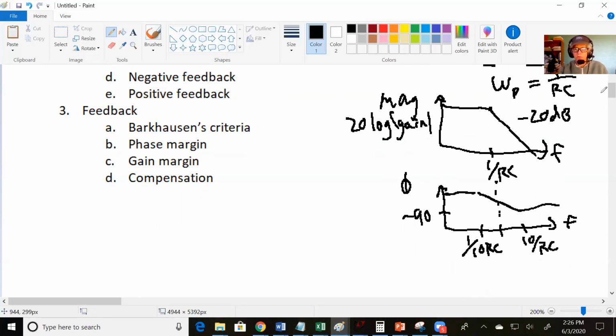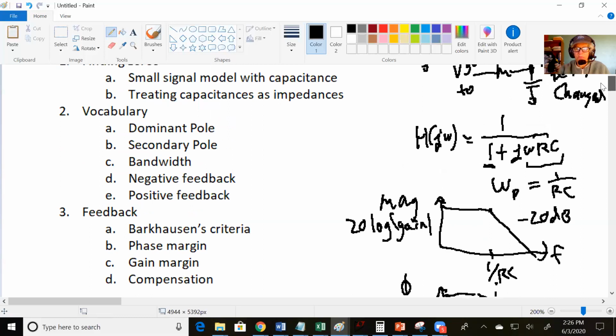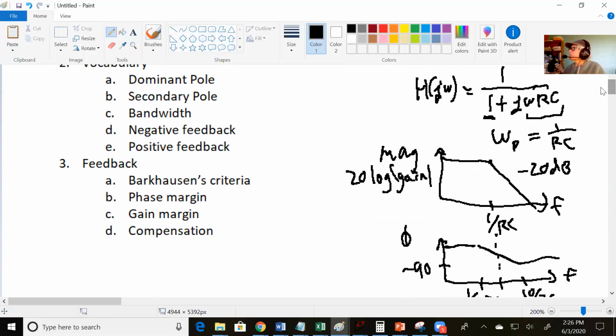But what was my point? Okay, so we've been able to find the pole basically using a quick method, just not having to do small signal analysis, just drawing in the capacitances on the transistor level circuit. But there's one value that you can't find without doing small signal analysis, and that's the zeros in this system. So let's do that math.